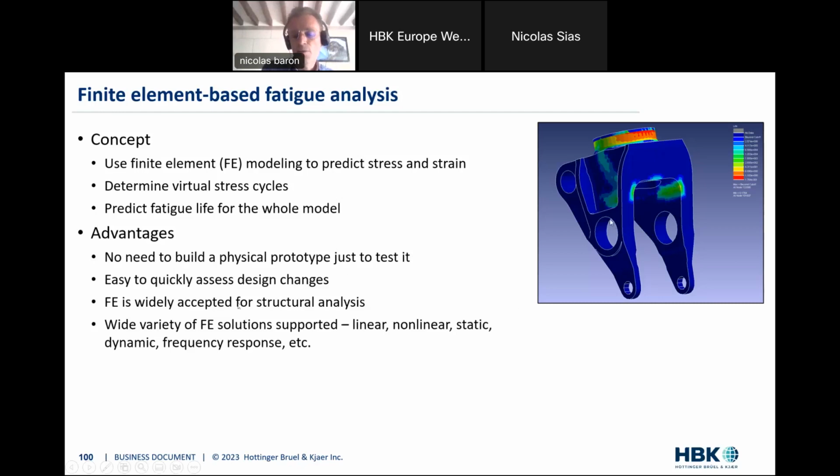It's very easy to modify the radius, to change the thickness, to have a new mesh, a new calculation. Just in a day or two, you do that, and you have your new fatigue result calculated very quickly, without needing to instrument with strain gauges, which might take quite some time. And in the software, within nCode, it is Design Life that addresses numerical calculation. We have various FE solutions supported. We can address dynamic calculations, linear of course, frequency response solvers. There is a lot you can do within Design Life.